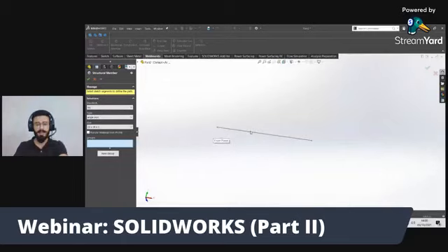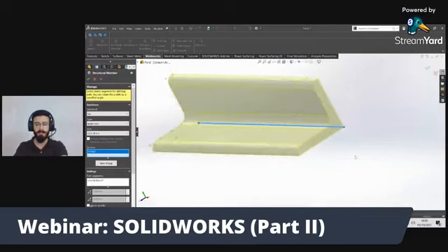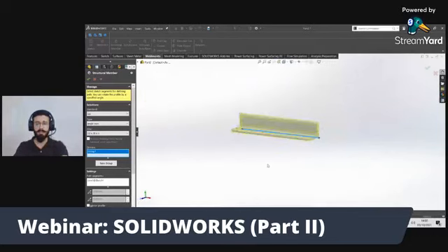Here, I just made a single straight horizontal line. This is easy, just select it, and this is how it's done. See, the angular beam is made. It's very simple if the line is just a straight line. But if the line is a curve, different curves, then it will be kind of difficult. I will show you all the types of beams or weldments available here in SolidWorks. Then I will show you some different kinds of curves to make it easy for you.